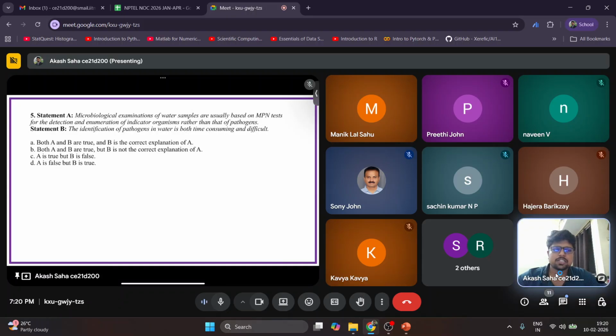Yeah, that was actually a very good point. So you have to take care of these things. Sometimes the discharge will be given as volume, sometimes as volume per day or per some unit time. If they might have written 1200 meter cube for a 12-hour cycle, then you have to do it accordingly. So be careful of that.